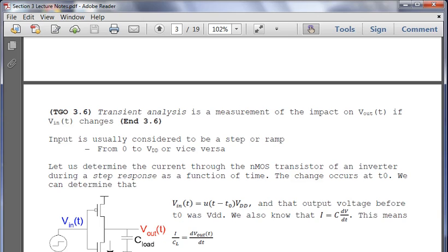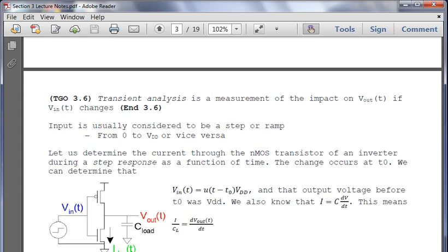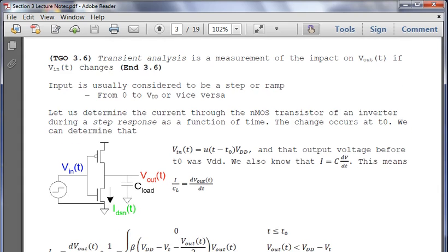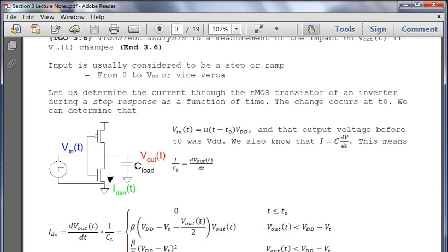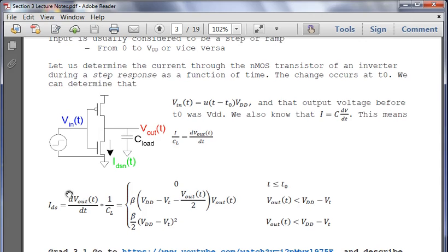In the previous session, we used this relationship to prove a lot of our beta ratios and what the voltages contribute to our drain source current at any given moment in the linear, cutoff and saturation regions. We're going to apply what we know here to figure out the direct relationship between the drain source current and the rate of change of voltage.